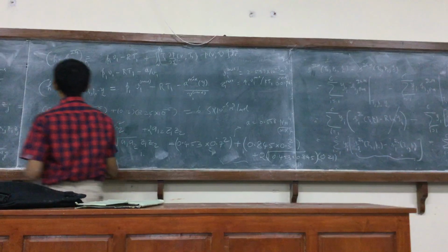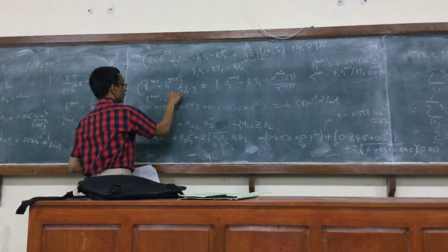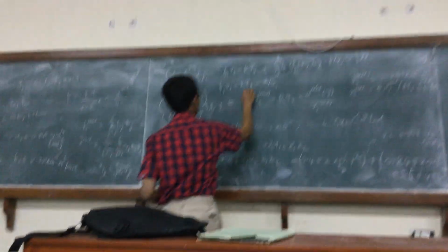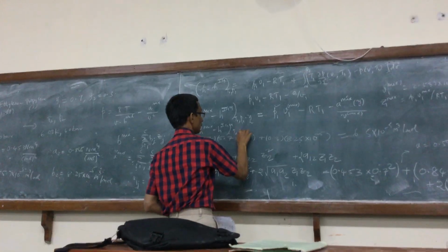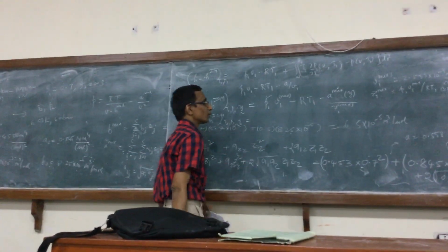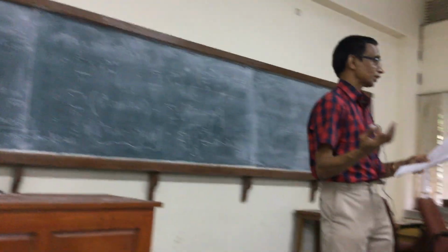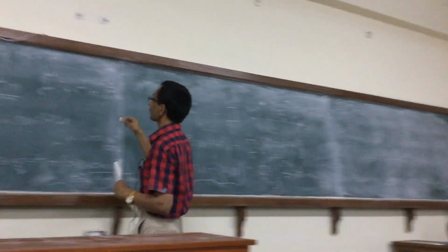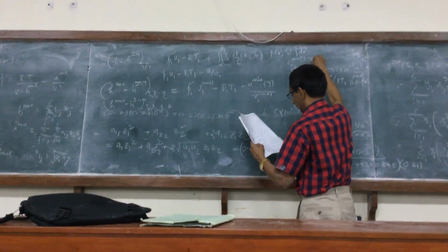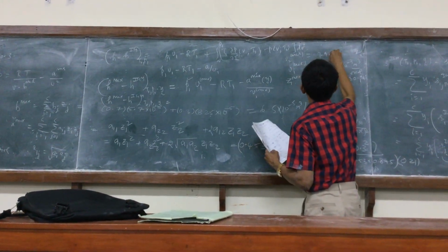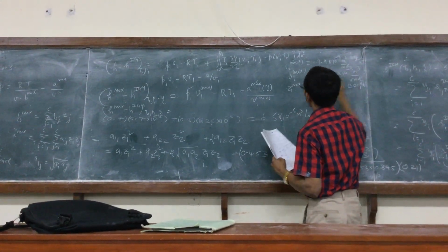So we have that, and now the calculation for state 2. Here obviously I would put T1 and P1 as given, 323 and 10 bar, and P2, T2. The V2 mix will change, not because the composition is changing, but because the pressure and temperature are changing. Now V2 mix, I have also calculated. These are the most difficult parts of the calculation. So I am giving you the answer: 7.9 times 10 power minus 4 meter cube per mole.